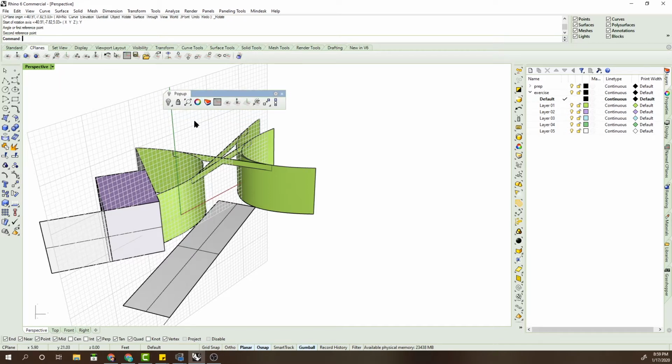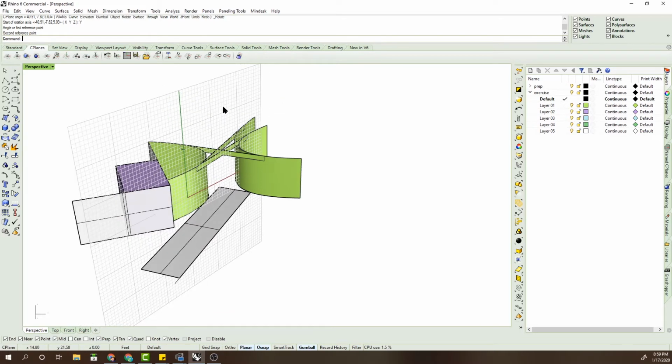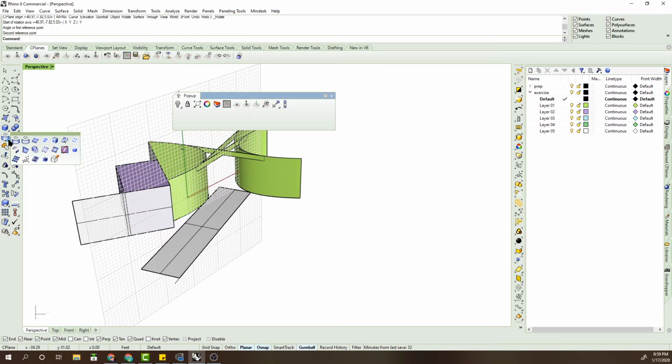Okay, so I've changed this around, but there's some defaults in here. And again, if I just middle mouse, boom, and I click and hold that little section there, it now sticks. It's called the pop-up menu there. And now I can make this a little bit bigger. And if I want to go grab other commands that are my favorites, let's do something else here. Let's just say I love the extrude by surface. So let's just say I like this one.